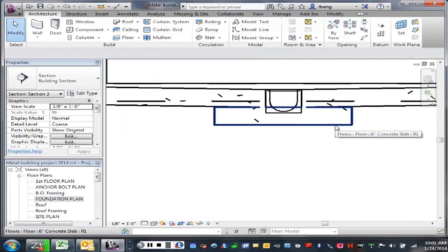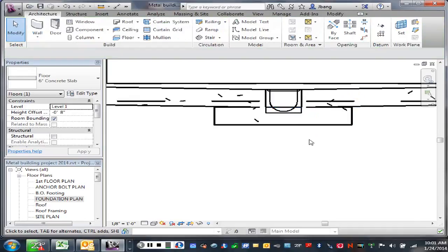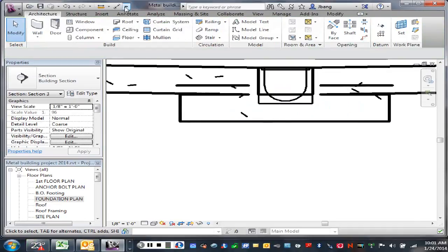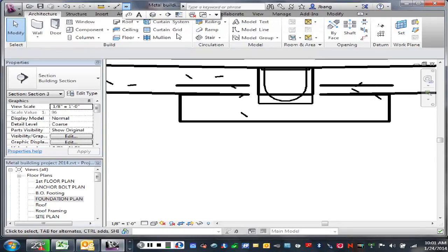Is it important to make it bigger than the drain hole itself? Yeah, the concrete would have to go down and around it, so the whole drain is encased in the concrete. Okay, so it should go past the drain, basically, is what I'm asking. Yeah. Any specific distance, how far, or a couple inches? I would say if the slab is 6 inches, you'd want to go 6 inches outside of it on each side. That'd be fine, sure.